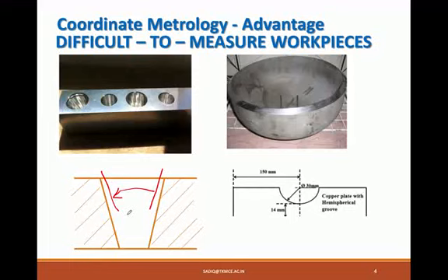the angle of taper can be given by the system based on the computation. Again, can you suggest any method to find the radius of this dish? It's a simple workpiece, right? Simple piece. But conventionally, there is no easy method to identify the radius of curvature for this, and for that, again we can use CMM, bring the tip on and pick many points on this.